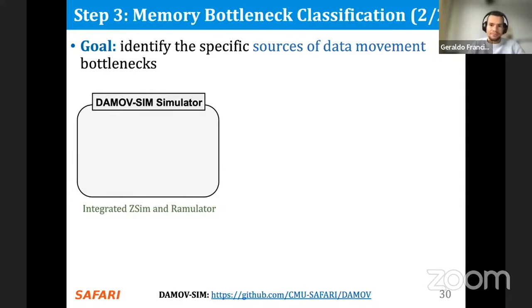To this end, we build a framework that integrates the ZSim CPU simulator with the Ramulator memory simulator to produce a fast, scalable, and cycle-accurate open-source simulator called DAMOV-SIM. We use ZSim to simulate the core microarchitecture, cache hierarchy, coherence protocols, and prefetchers. And we use Ramulator to simulate the DRAM architecture, memory controllers, and memory accesses.